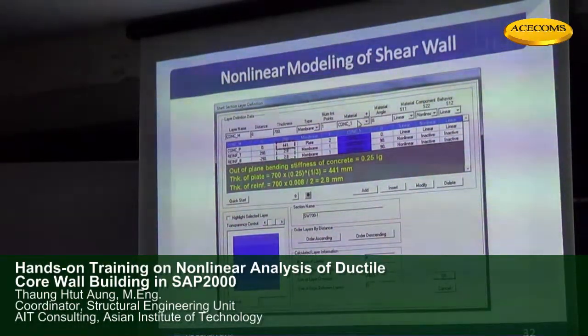So we have to check this F11. Not only F11 stresses, but if the load is coming in this direction, there will be F22 stress. So we reduce the F11 and F22 of the diaphragm to 0.5. For the shear rigidity, sorry, this one is not correct. It should be F12. Not only the flexural stresses, it will generate shear stresses in this direction like a beam.